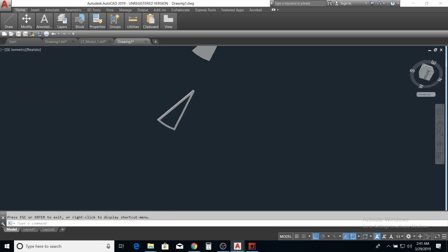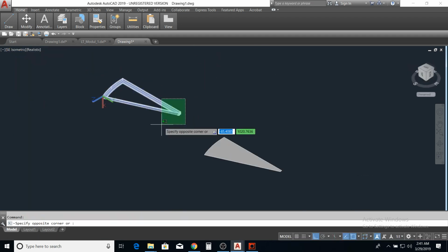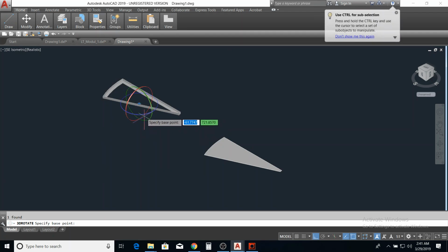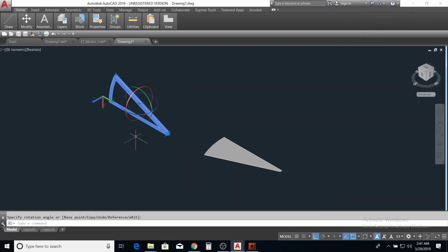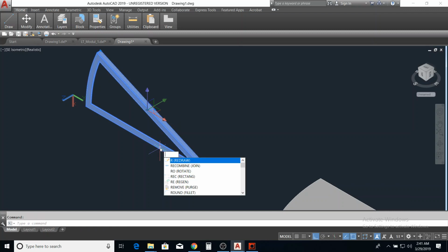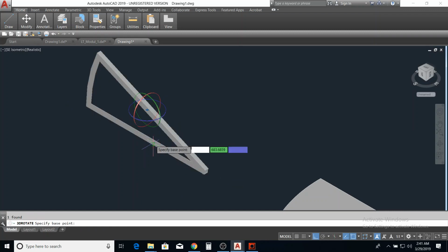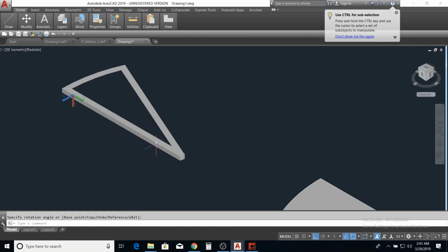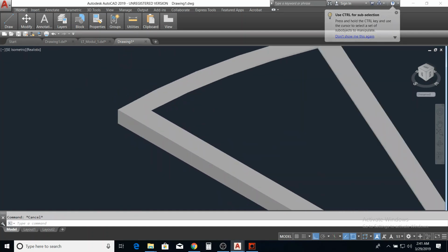Back, SE isometric. What I'm going to do is that I can simply mirror this, or maybe I can rotate it, any of them. But before the rotation, I need to use the 3D rotate command. So I want to rotate it about an axis, the red one, for instance. Now I need to make again 3D rotate is important about again. Then we are good to go.